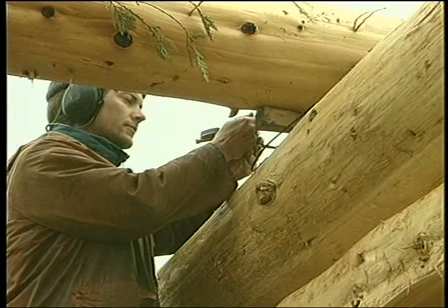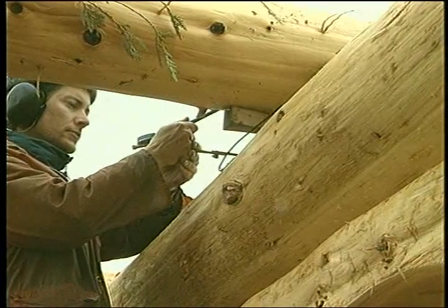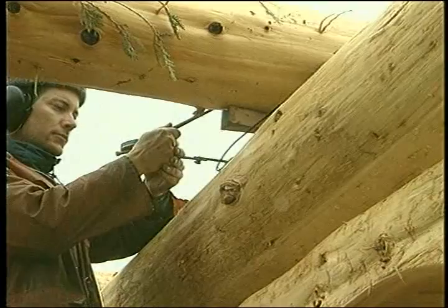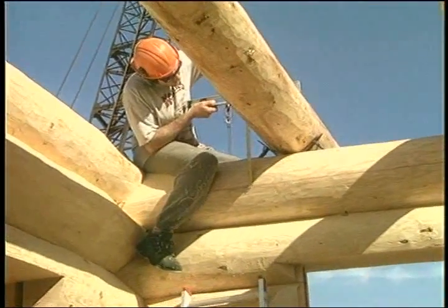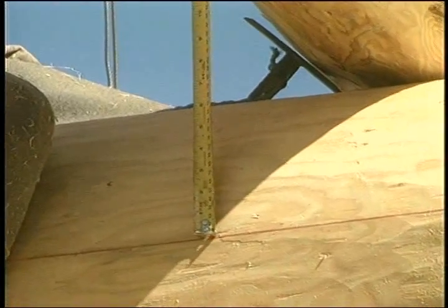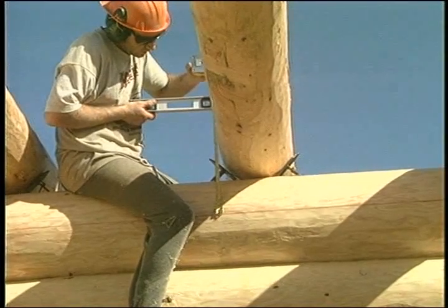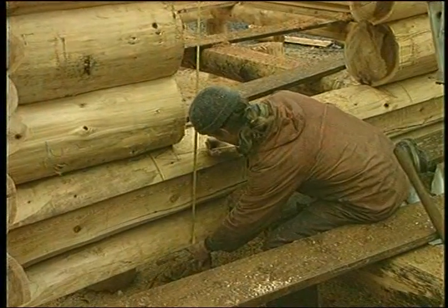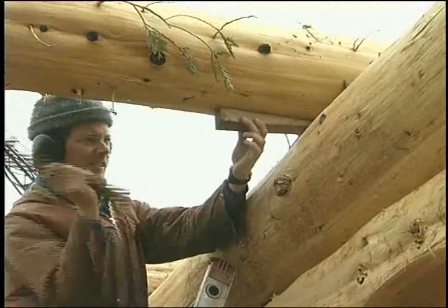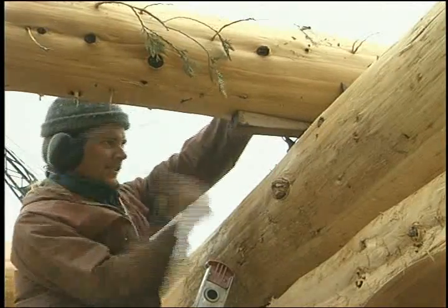Now you are going to scribe the joist down so that the tops of each will be the same height above your reference line. To do this, place a level across the large end of what you judge to be the smaller joist. Measure from the bottom of the level to the reference line. Let's say this turns out to be 650 millimeters. Go to the small end of the joist and wedge it up until this end is also 650 millimeters above the reference line.